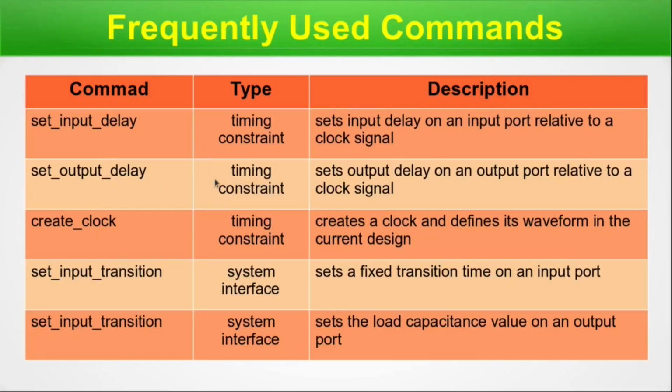Set_output_delay. This is also a timing constraint. It sets the output delay of an output port relative to a clock signal. So you have a clock in both cases, and with these two commands you can set the input delay as well as the output delay.